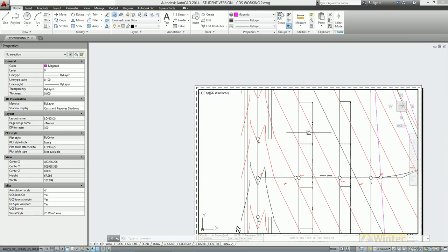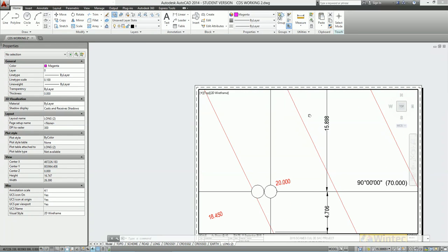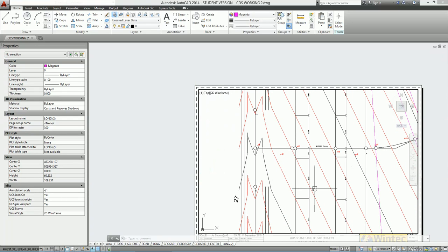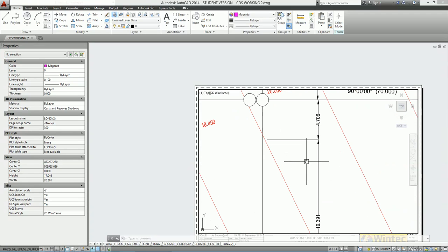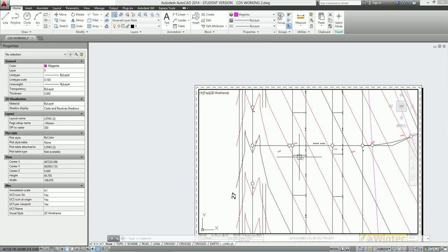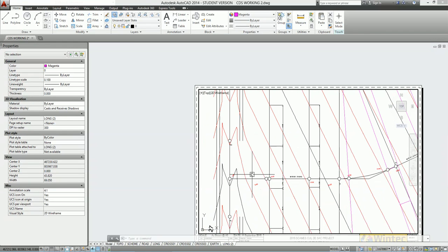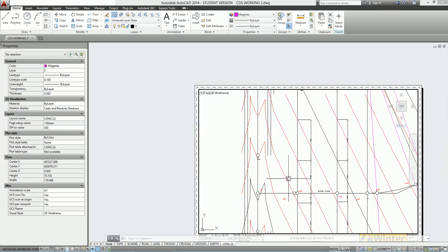You can of course document just using the dimensioning tools. You can document the intersections of the cross-section line with the particular contours. You could perhaps note that down into an Excel spreadsheet and then just plot up the cross-sections like so. And so I've dimensioned them there, and then you can see that that's 27.246, so 27.6, 27.8. You could do that there.